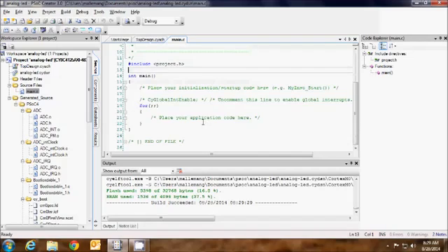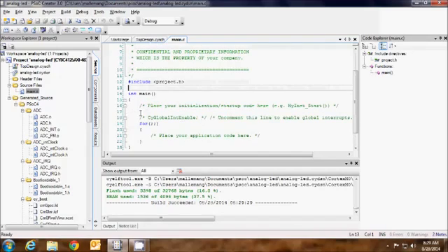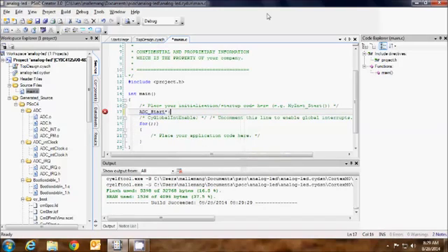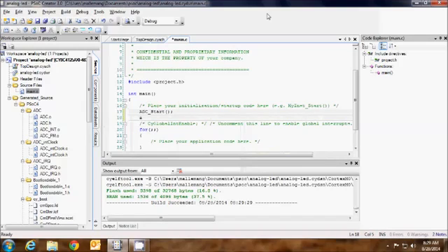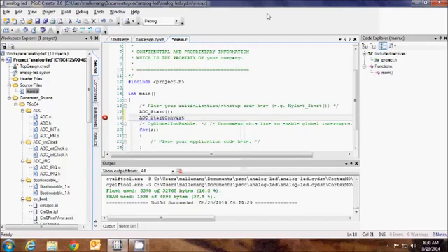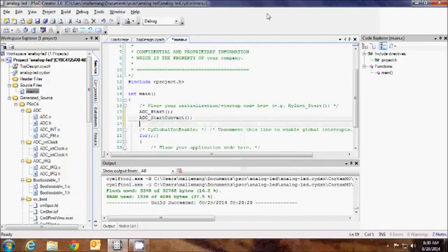Okay, so what I'm going to do is the overhead that I need to do for the A to D controller, analog to digital converter, I mean. First you have to start the overall subsystem, then you have to start the conversion. And I'm going to let mine run in free running mode, as opposed to start, wait till it's done and get result. I'm just going to free run it asynchronously. So there you go, start and start convert. That's what you've got to put in your initialization. And then in your loop down below, we'll simply get the value.